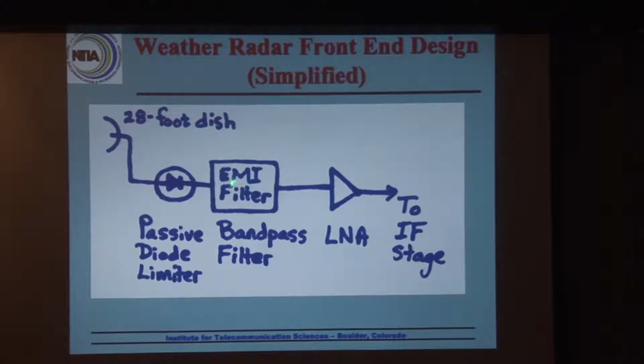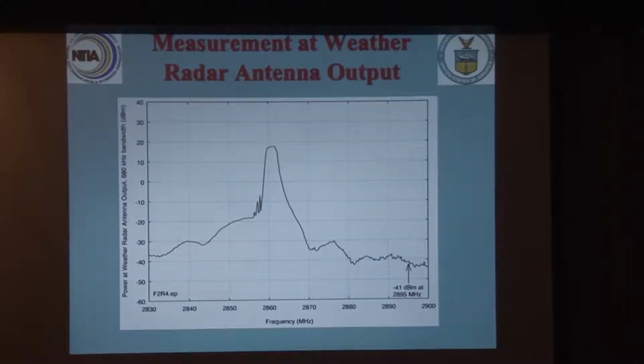There's no need to protect a bandpass filter from high energy. You cannot burn out a bandpass filter. Well, if you burn out the bandpass filter, you better be in a bunker, because something's going horribly wrong at the radar site. Direct lightning strike. Right. Is this intended for direct lightning strike? Not really lightning strikes. The Navy uses them. Although this is a terrestrial weather radar, they feel it protects them from the problem with strong incoming signals.